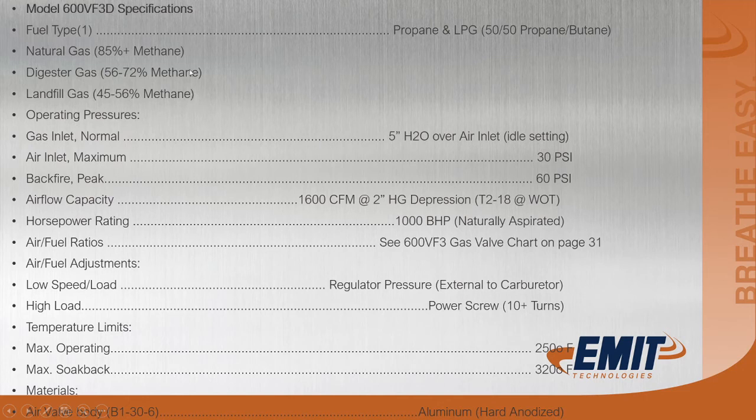You can go to the book, like on a Vari-Fuel 600, and you get all the specs. And one of the specs I want to show you here is so many guys or gals, whatever, service techs, will set the pressure much too high when the engine's loaded and then they don't start. These mixers are not supposed to have over 5 inches of water column. There isn't a normal mixer out there. There's a few brands that maybe go a little higher. There's one that's built for an air-fuel ratio controller in it that's higher. But as a rule, carburetors are not supposed to have more than 5 inches of water column on the inlet of that carburetor. They get very difficult starting.